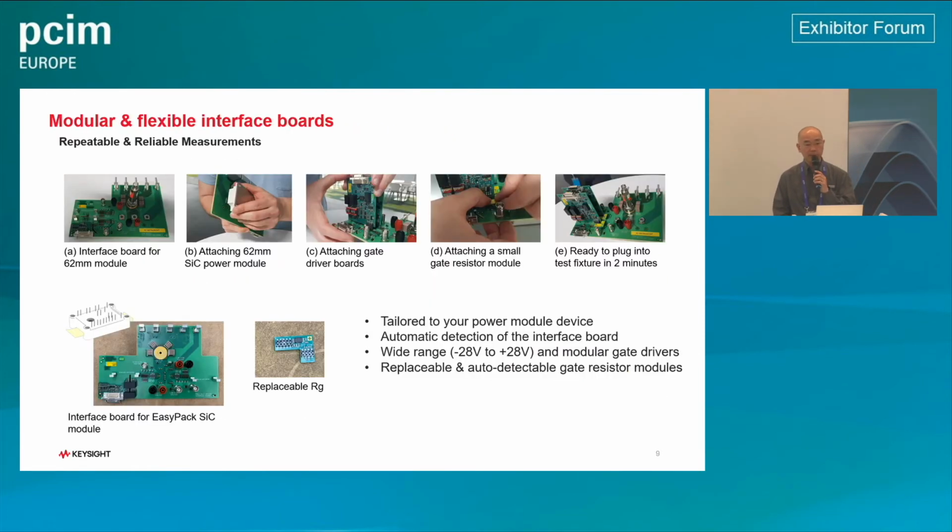All right, so PD1550A is kind of a standard off-the-shelf type test instrument or tester. And so you can use most of the features without doing any work. But because the power module has different form factors, one thing has to be custom, which is the interface board. There is a lot of know-how and expertise necessary to make this interface board.